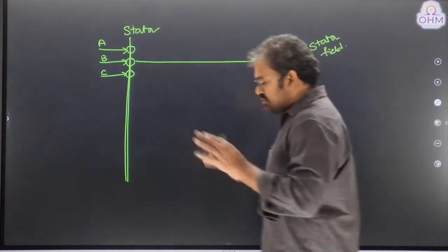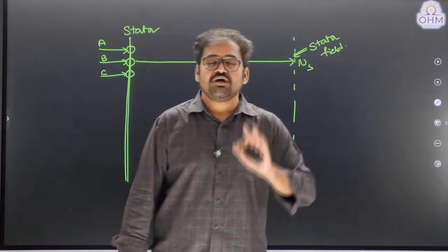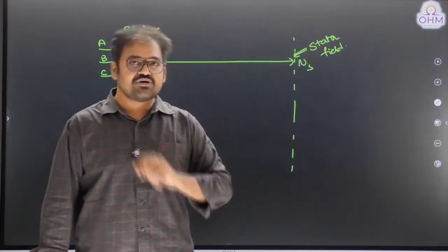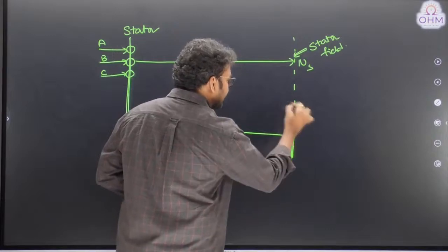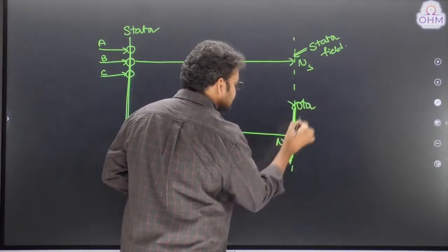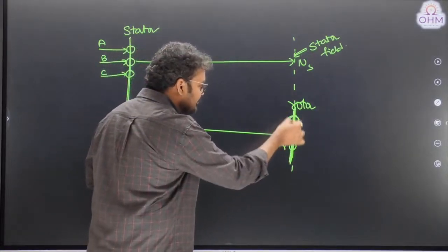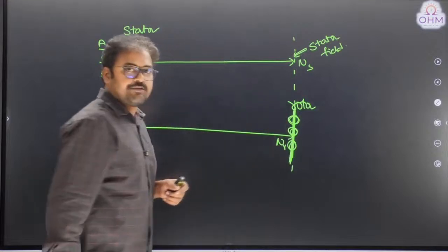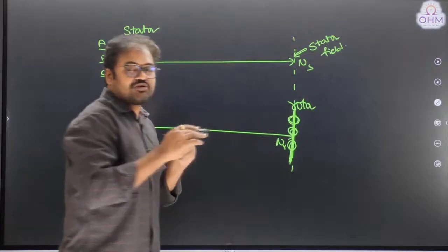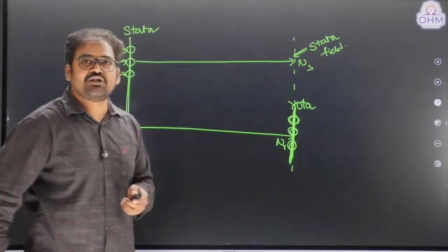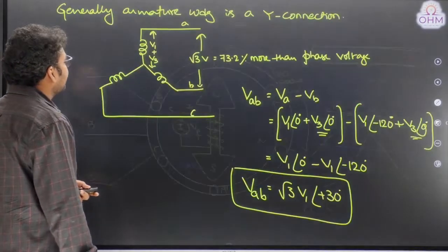Now, the rotor will rotate at what speed? Ideally, under steady state condition, the rotor will always rotate at synchronous speed, right? This is the ideal case, steady state condition. And this rotor will have distributed damper conductors. Now one more thing: when the rotor is rotating, which torque will support the rotation and which torque will oppose the rotation?